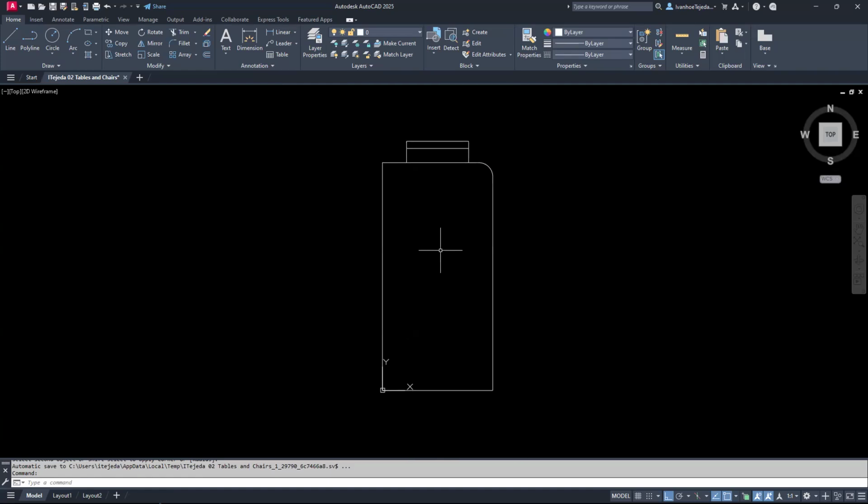I'm going to zoom out, and then I need to repeat this command. But I'm going to show you how to do it all at once here. So I'm going to repeat the fillet command, so I'll enter. It is already set to 4 inches if you look at the command line, the radius. And then there's another option, and let me just use my down arrow right now because it's possible. So the down arrow shows me the same options that I see on the command line right here on screen.